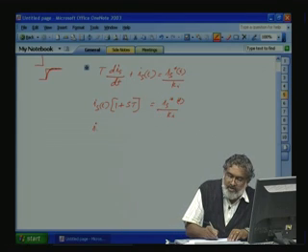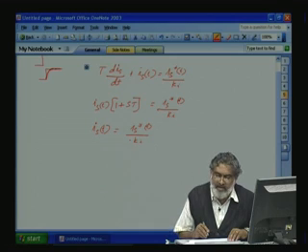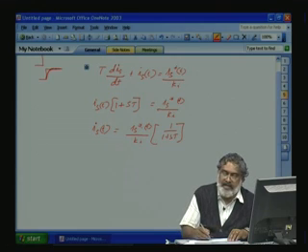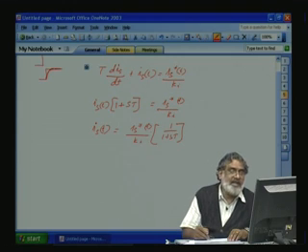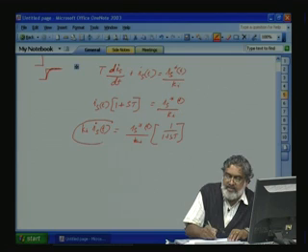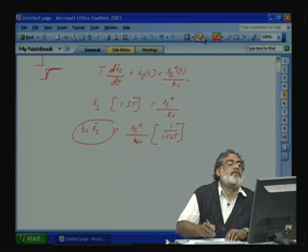That means the output with respect to input will be is star t divided by ki into 1 by 1 plus sT. So, for any change in is star t, ist, that is the feedback current, with the gain factor ki, will vary in the form of a first order lag.